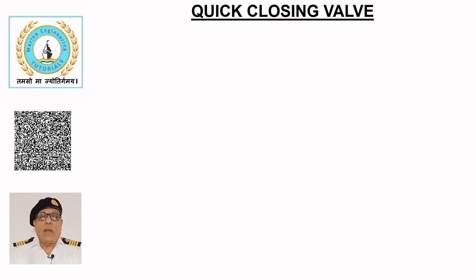Quick closing valve. Ships' fuel oil settling, service, and storage tanks, as well as lubricating oil tanks located in high risk areas, must be fitted with valves that can be closed rapidly and remotely in the event of an emergency such as fire.